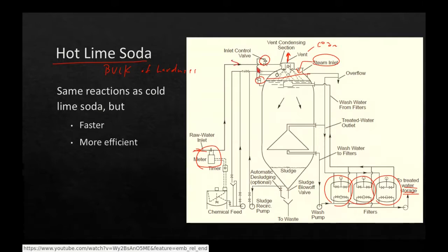So the water comes in, we got a level control, water goes out. Now the water that leaves gets filtered, and in this case, they're showing it's repressurized in the way that it goes. By the way, because this is pressurized with steam, what we have is an ASME code Section 8 pressure vessel. And so it's going to have relief valves and all that kind of neat stuff.